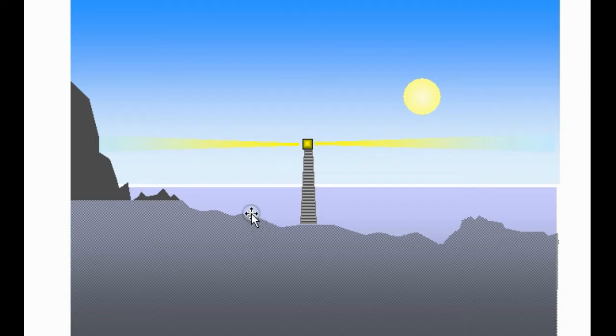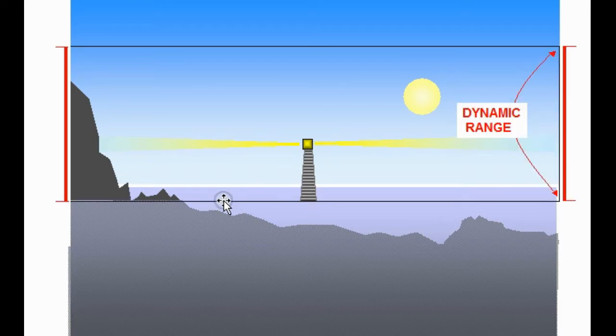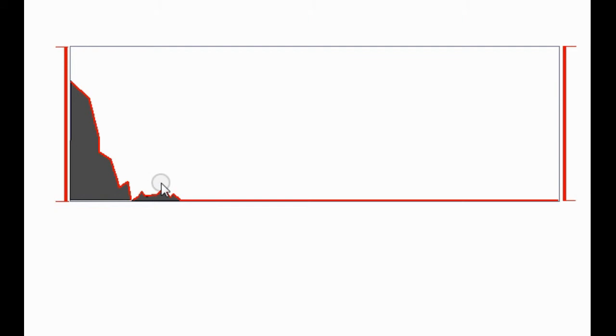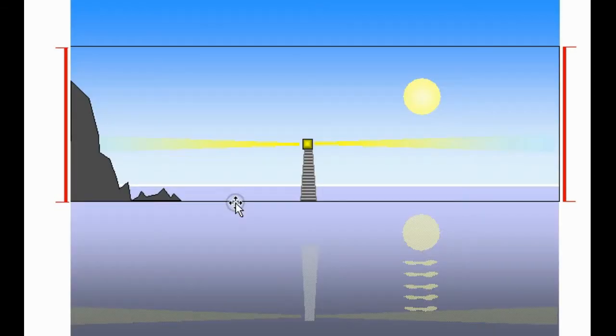Now our analyzer, like all other analyzers, has so much dynamic range. The dynamic range dictates the minimum level we can see and the maximum level we can see. So our signals need to reside in this window. We cannot change the height of this window, but we can move it using the attenuator. Now at the current setting, our spectrum would look just like this. So much of the lower level signals is lost from view.